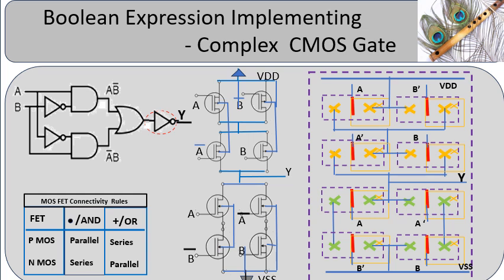To visualize the transistor level schematic, break the complex logic expression into sub-blocks using basic gates like AND or NOT gates. Create the desired logical functionality by employing pull-up and pull-down network. Join the pull-up and pull-down networks to create the stick diagram of the design. The stick diagram shown in the figure is for conceptual purpose only. However, in practice, stacking of transistors is to be avoided.